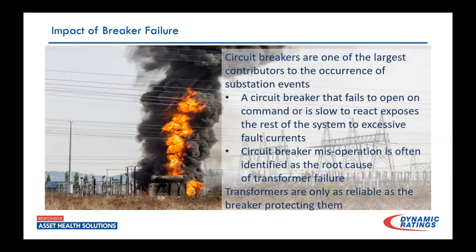And I found that our CAIDI and SAIDI times were really increasing rapidly the last few years I was at the company, and when we got to looking into it, we found that a lot of that was due to breaker misoperations. We were an offline test only type of company, just traditional timing and travel tests, ductor type tests. That was what we were doing to try our breakers, and we tested on about a 5-year cyclic maintenance.